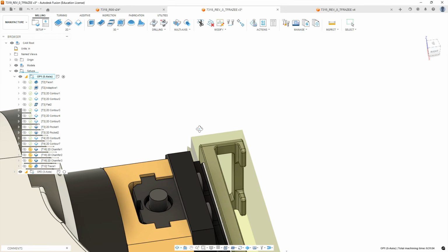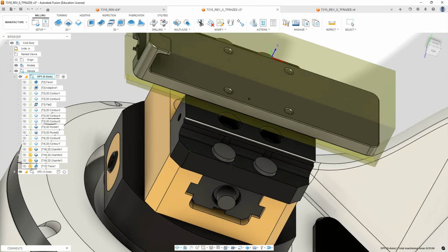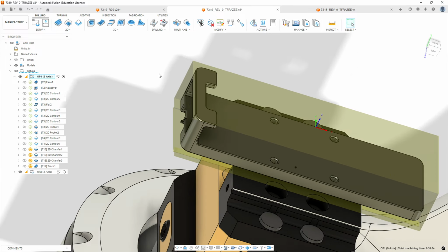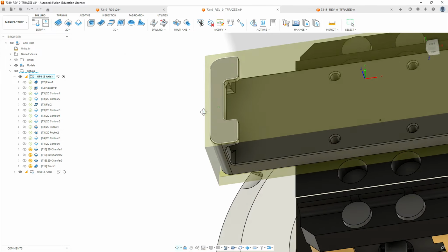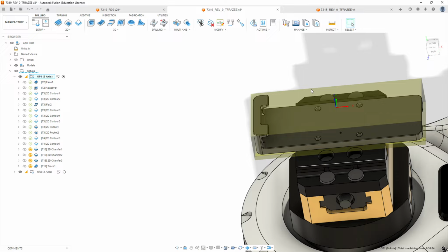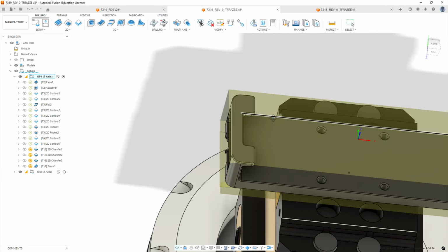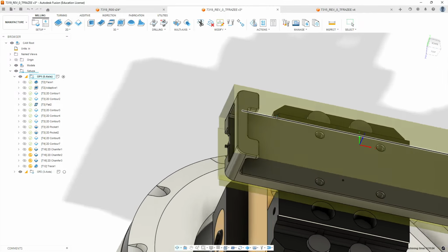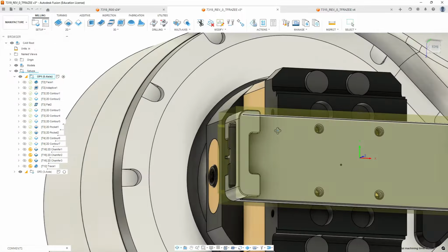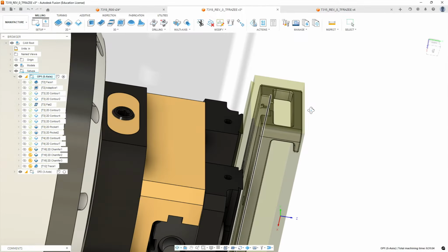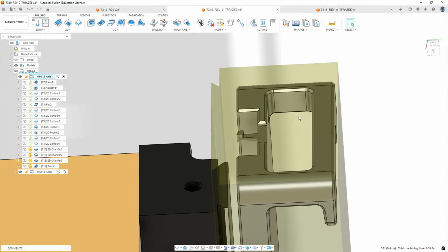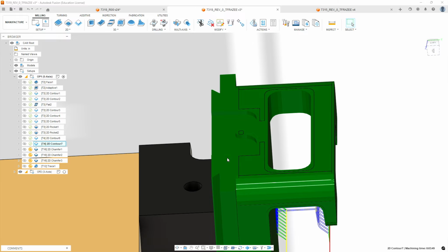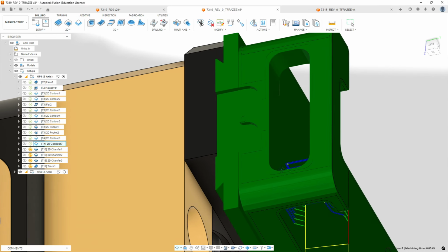Okay, so now we've gotten all the 1/8 inch cutter work regenerated, and we need to do the additional 1/8 inch end mill work that occurs on this part. So we need to look at what else we need to do. We have all these features on the end. We've rough cut through a pocket for this window. We've rough cut around this feature here. We've rough cut out through here. So up to this point, this is what our part looks like.